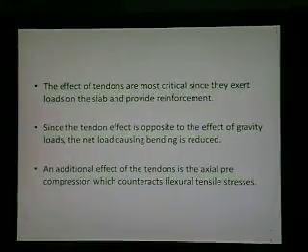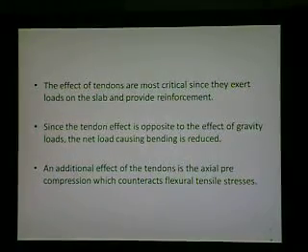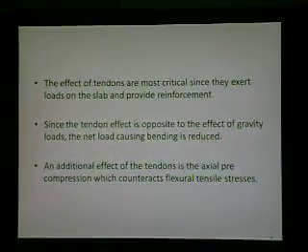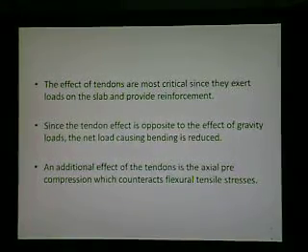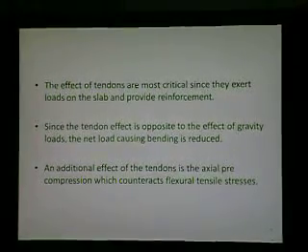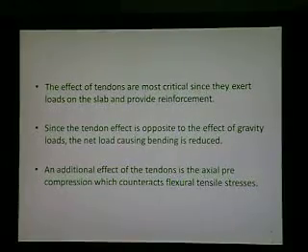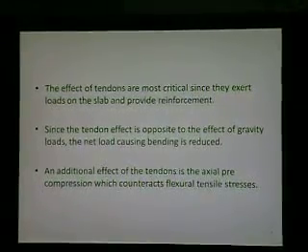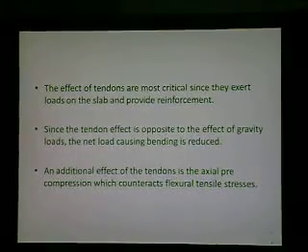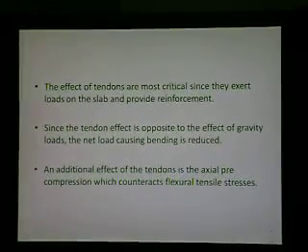The effect of tendons are most critical since they exert loads on the slab and provide reinforcement. Since the tendon effect is opposite to the effect of gravity, the net load causing bending is reduced. An additional effect of the tendons is the axial precompression, which counteracts flexure tensile stresses.